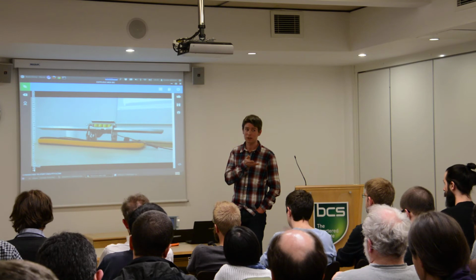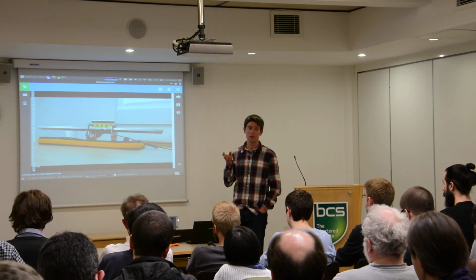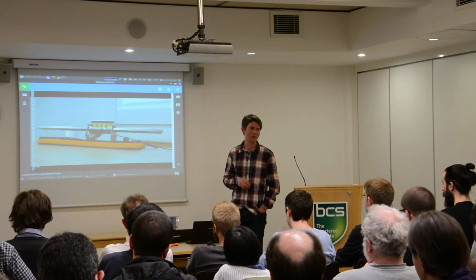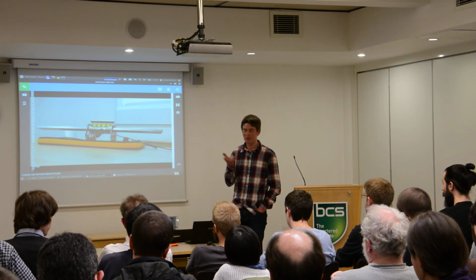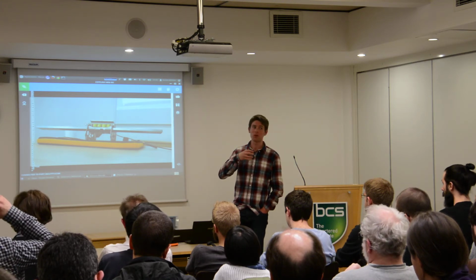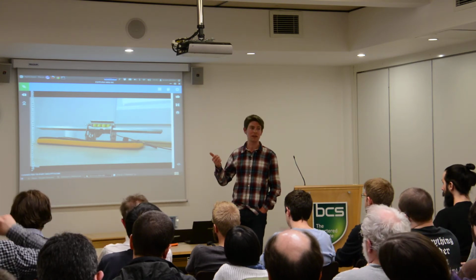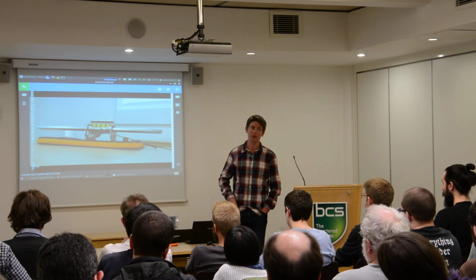It's the hardware abstraction layer though, which does take an awful lot of time, as I'm sure Bogdan will know. So yes, you can get it running, but if you want to have good SPI, I2C, timers, and all the rest of it, it'll take a long time.